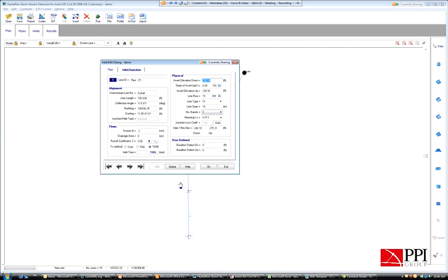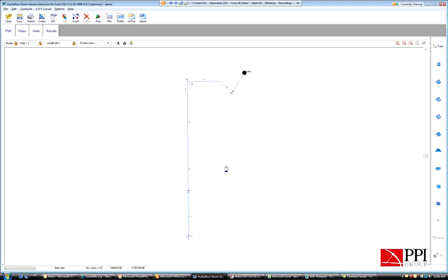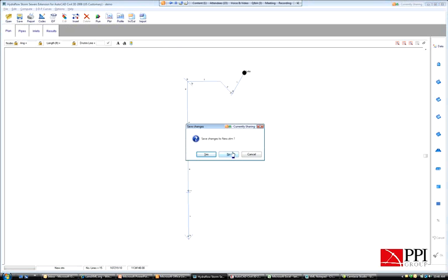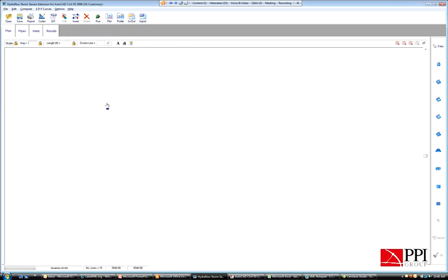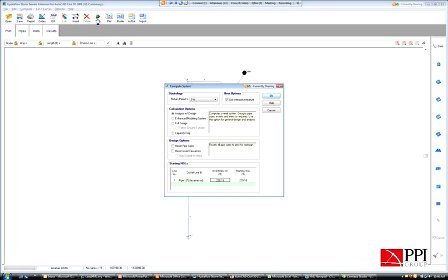So then, I'm seeing the time near here, so just to move along. I'm going to say okay with that, and this will give you, let me just real quick open up that one that you saw open when I first got in here. So once everything is built within that, then you can come in here and run, compute the system. You can do full design, analysis with design. Let's do a full design and have it reset our pipe sizes for us as it moves through there.